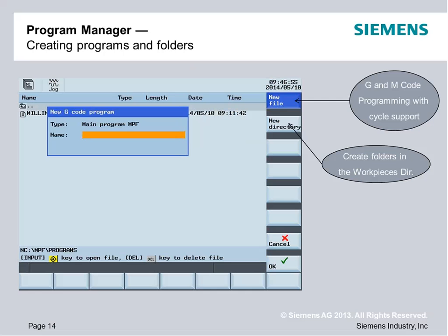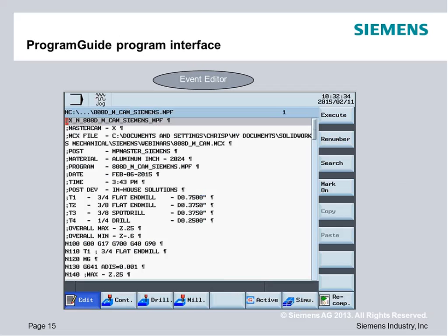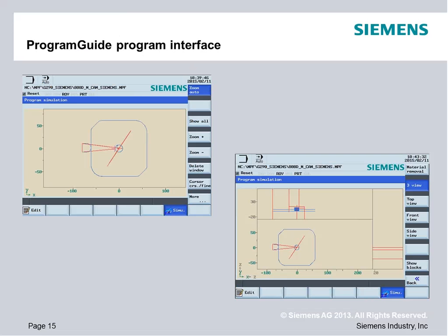TSM allows us to do quick tool changes. If I want to change what tool is physically in the machine, right now I see that I have T0, so there's no tool physically selected in the machine. If I want to fire up my spindle, turn on my spindle, it really keeps us from having to go to an MDI type of protocol to be able to do some of these functions. I can go into measure workpiece, and this allows me to set zeros or set offsets.